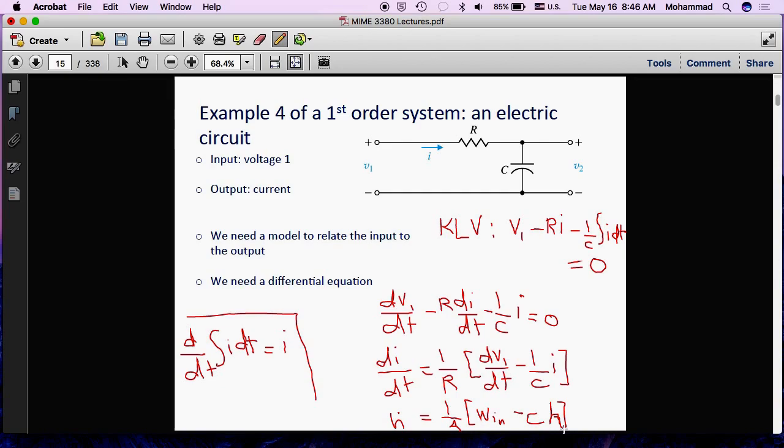In other words, if voltage is stationary, if we attach a battery which can provide, at least in theory, a constant level of voltage, and there is no current at the beginning, would current change at all? According to this equation, it would not. And that's a property of a capacitor. You need fluctuation in voltage in order to get any current to pass through the system.